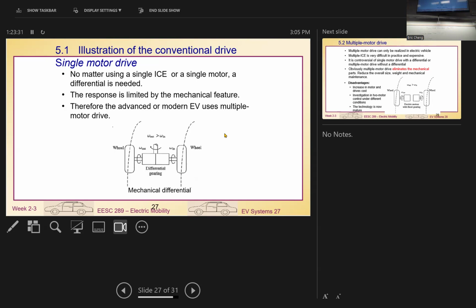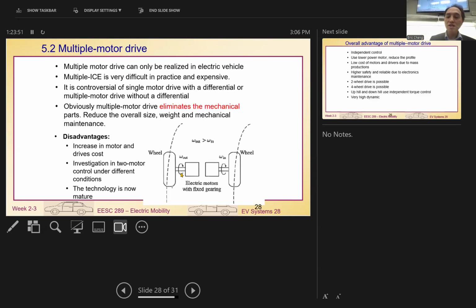Conventional mechanical differential can do the job, but not really nicely, because you can't have really good control or good variation of the wheel speed. But that's the technology of 30 years ago. Now we use differential motors, and we can change all this. We can use two motors like this, one for each wheel. We can control torque and speed however we like. So that's why we're able to control the vehicle nicely.